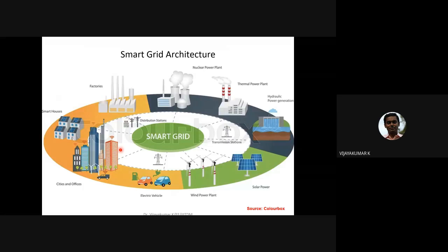In this case, for example, we can take the smart lighting system. Earlier, normally they would use sensors to measure the intensity of the light, and turn the lights on and off. Now, in every building and every floor, we have surveillance cameras, right? So by using the surveillance camera, you can control the lighting of the building. Yes, it is possible. Why? Because we can take the image or video from the surveillance camera and process it using image processing techniques, and you can get to know the intensity of the light in the images or videos.